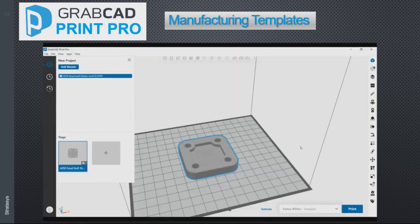Now let's use the same part to set up a manufacturing template. What a manufacturing template does is it takes all the settings that you input into GrabCAD Print and it exports them into a file that you can either use later or send to somebody else. So if you need to build iterations of the same type of part over and over with the same settings, this will save you a ton of time setting up your builds. And it's also great if you're building parts at different facilities that you can share these templates back and forth and make sure that you get consistent results.